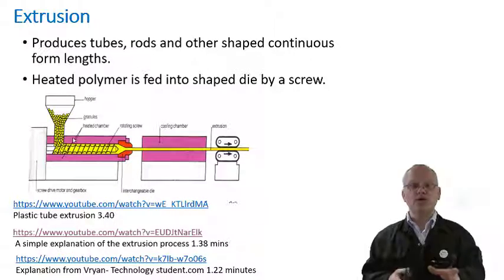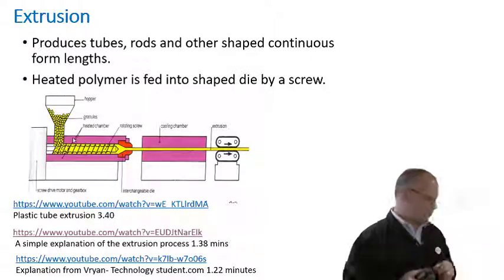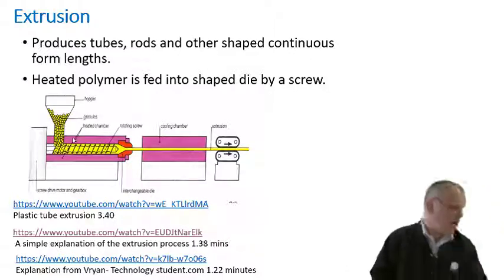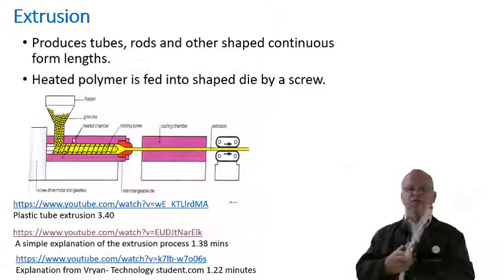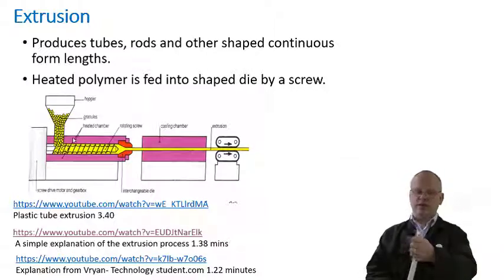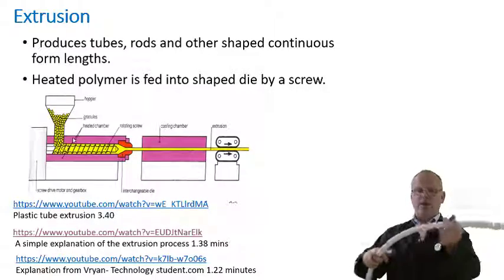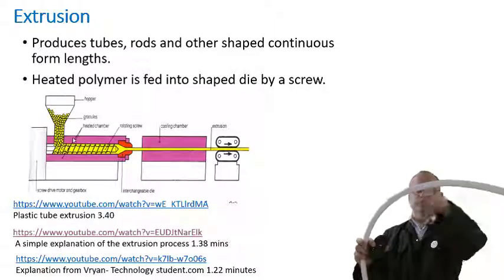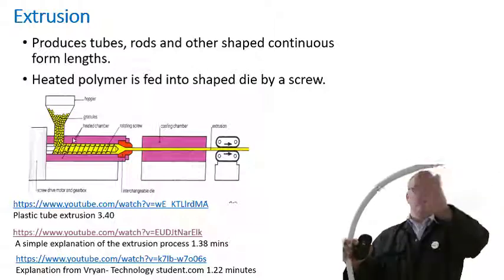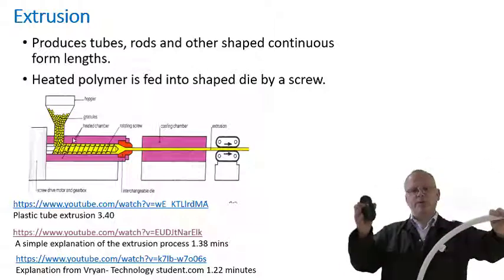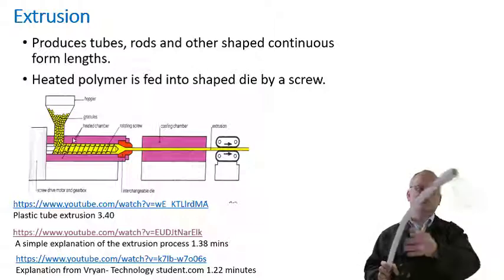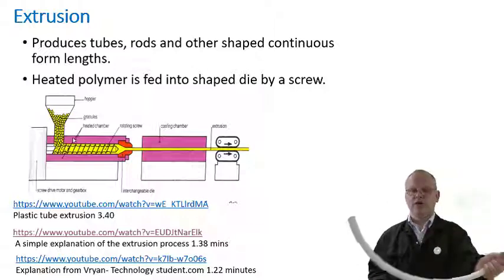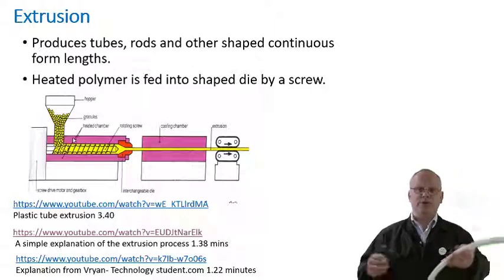So your examples of extruded products are, I've got a bit of PVC pipe, this is polyvinyl chloride pipe. In fact, all of my products are PVC. So you've got a long hollow section, and that would be continuous. So it would feed through the machine, it would actually come out straight. It would be fed through the machine, and it would continue, and it would be chopped to length. So this originally was bought as I think a 20-meter length, but certain extruded products could be longer, others could be shorter.